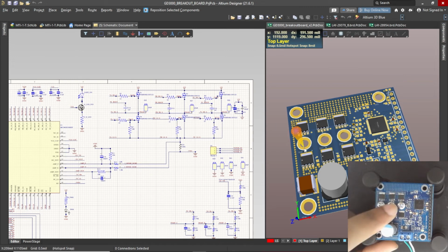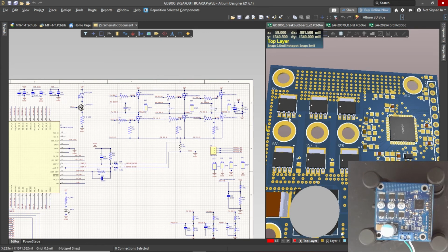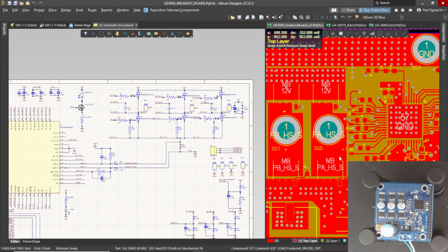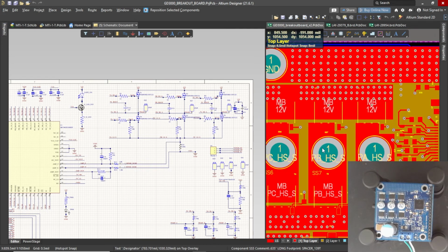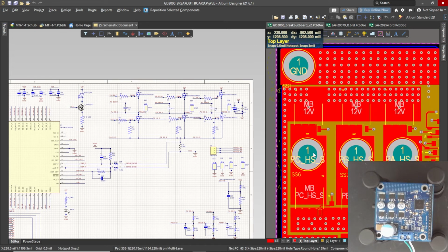And one of the things that I feel that I've not done a good job on is really making the trace widths of the gate drivers; they are causing a lot of issues. At least I feel that that's where I could really improve. There's not much symmetry. There are too many wires, and it's not really as clean as I would like it to be. And that's something that in this particular circuit I could actually improve.